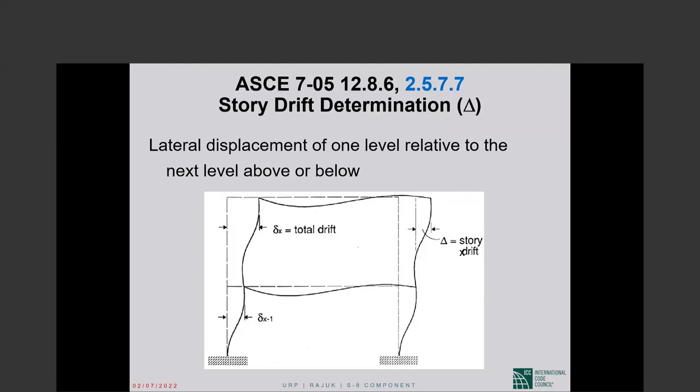One is where we impose a limit on interstory drift. That is more than life safety. We are now trying to prevent damage to non-structural elements or minimize damage to non-structural elements. We are trying to keep machinery that is mounted on our floors functioning.